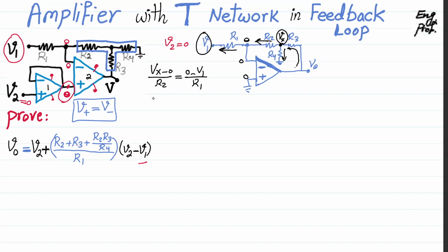The conclusion from these is what is well known, which is Vx over V1 is equal to negative R2 over R1. That is effectively the gain of the seemingly inverting amplifier that we see between V1 and Vx. Now, keep this as equation 1. But that's not the only KCL we can write. I can write a KCL from Vout as I am showing here.